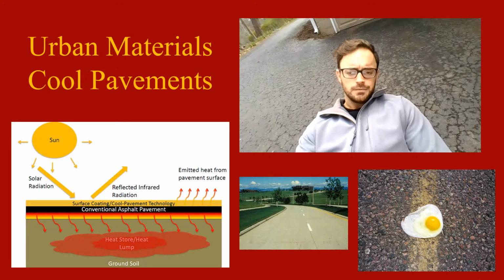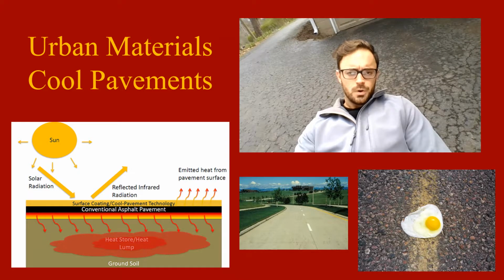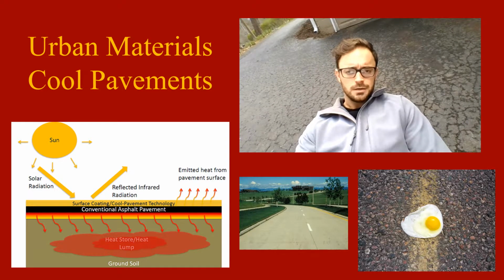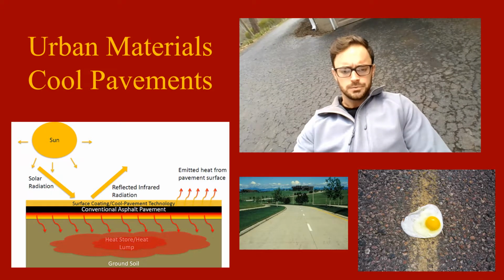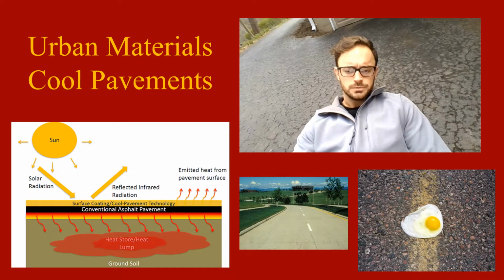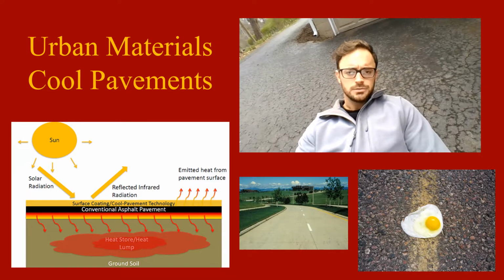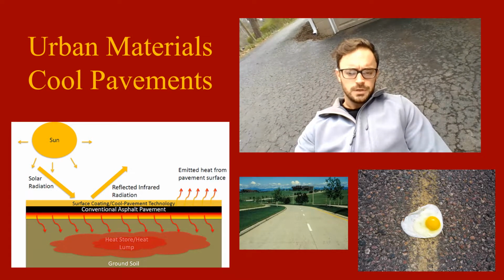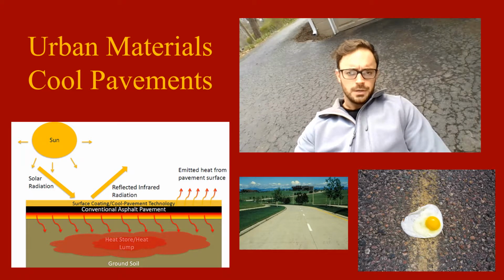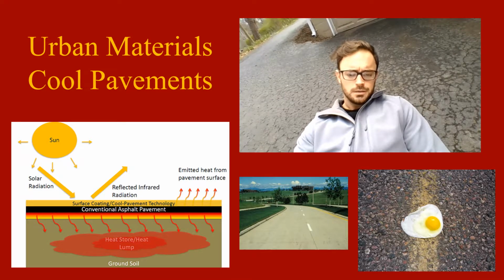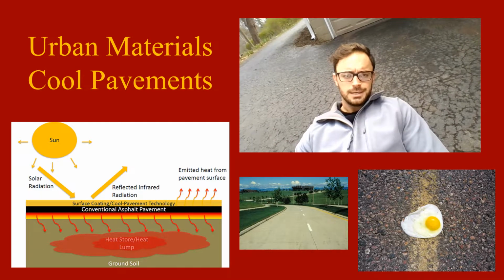It is important to take advantage of regular maintenance required for pavements and make the transition to a lighter colored surface then in order to be as cost effective as possible. Good maintenance practice calls for resurfacing a new road after about 10 years. Therefore, after these 10 years, all asphalt within Phoenix would be resurfaced with a higher albedo material. The transition to cool surfaces is a strategy that Phoenix must take in order to help mitigate its urban heat island.